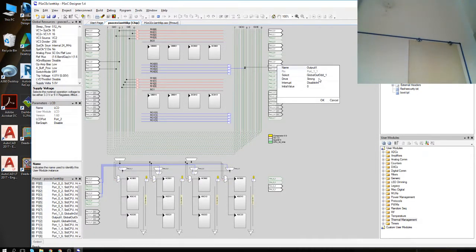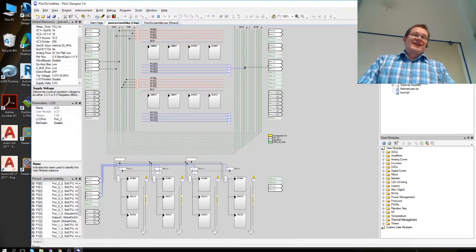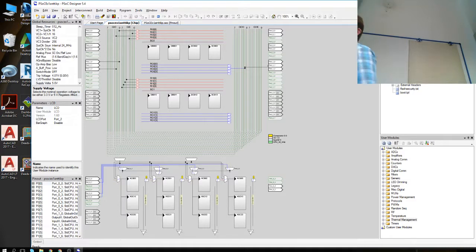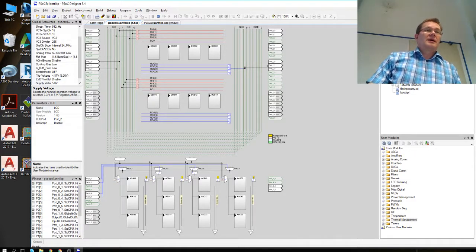So this tool is just a design tool to do most of that ugly stuff automatically. When I started doing my first microprocessor code, I had to actually initialize the processor, writing the assembly code there first. You don't want to do that, believe me. And the last line on boot.asm is actually to call the main routine, which is written in C.